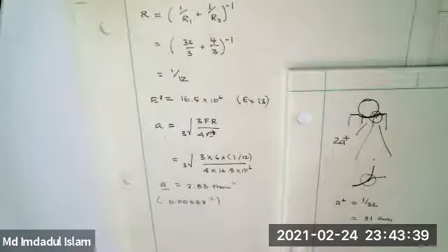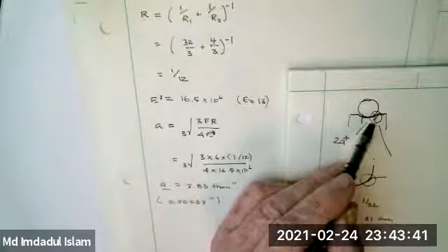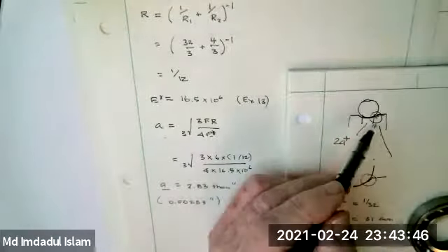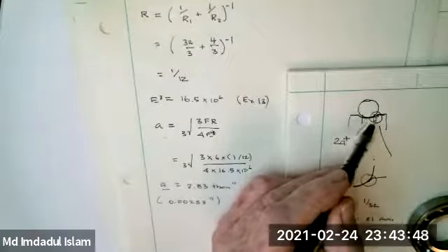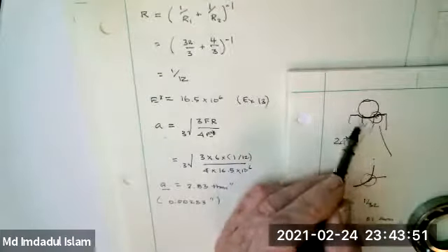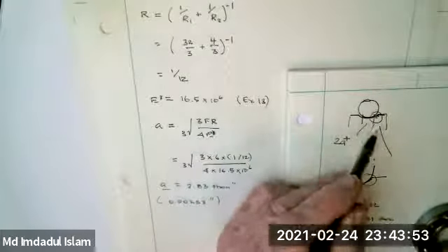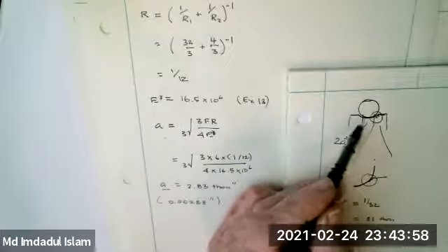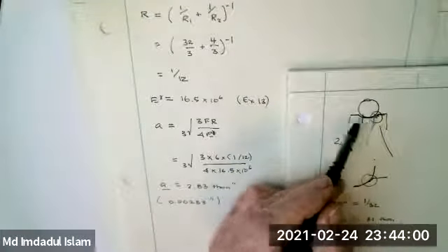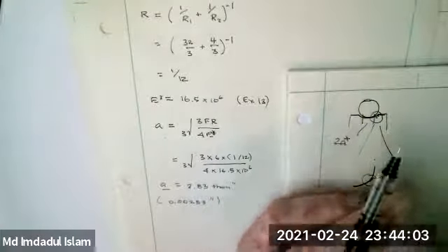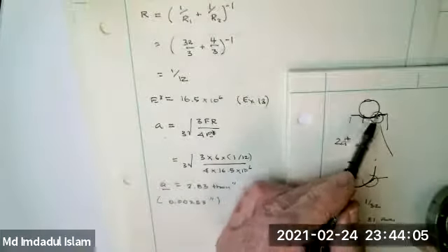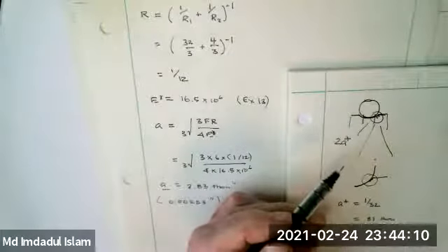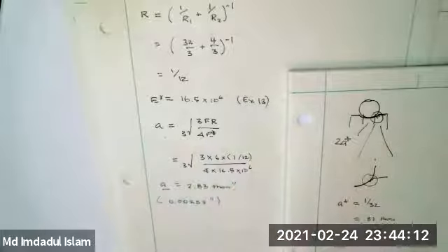Okay. So that's what you're going to do for these spherical ball bearings. Within one plane, they're both circular, so that's absolutely correct. This other plane, you just estimate the contact region by taking the groove and taking a little bit less than the groove. There are some detailed calculations on how you do this, but by and large, if you get the extent of the groove, you can get it very easily if you can take it apart. This thing doesn't come apart easily. But you can measure it, and then if you take, say, 80% of it, then that'll be that length there. Okay. That was an excellent question.